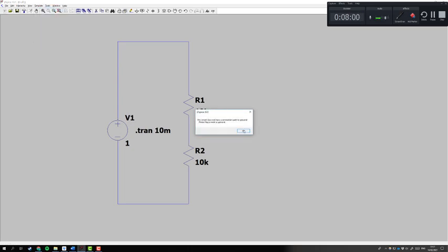And this circuit does not have a ground point. Now, this is a very important aspect of Spice. If you look at this simulation tool, this voltage has a positive and a negative, and a line is going through these resistors and down and back up again. So actually the circuit is complete. However, in the Spice tool, you always have to define a ground point. So let's put that in. So this is a ground, and we're going to connect it to the bottom, connect it in effect to that minus. So if you see that error, it's simply because you haven't put your ground in.